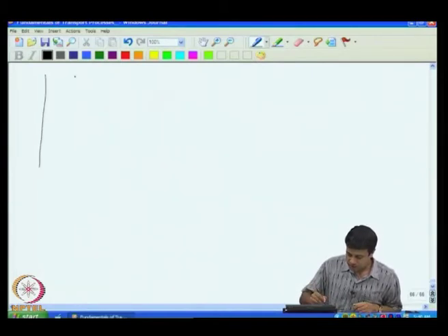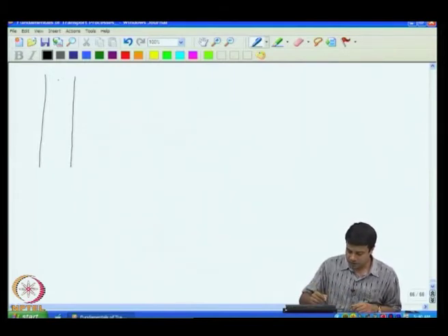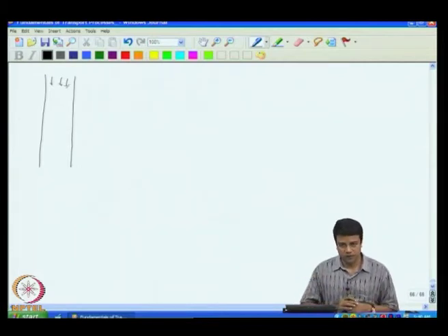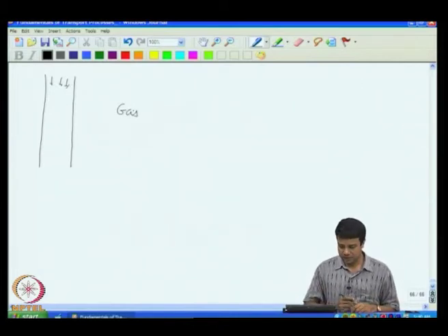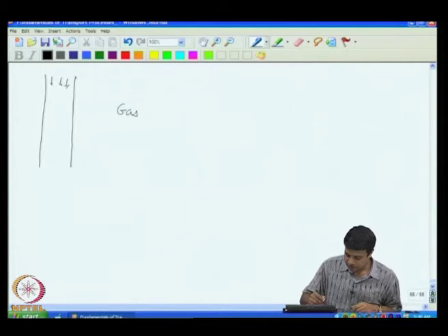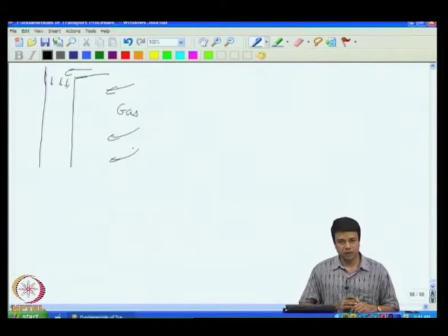And that is the mass transfer to a falling film of fluid. Let us say that I have a film of fluid falling downwards along the wall of some contactor, and there is gas here, there is gas at the surface. So, at the entrance, there is an entrance towards the fluid, and then it falls as a thin film along the wall, and it comes into contact with gas along the wall, and the idea is to dissolve this gas into this film of fluid.